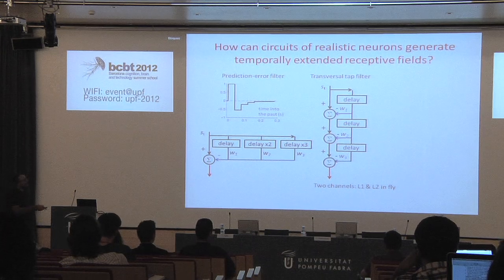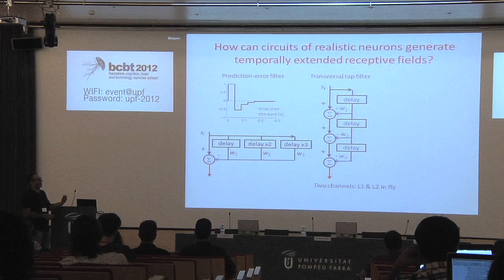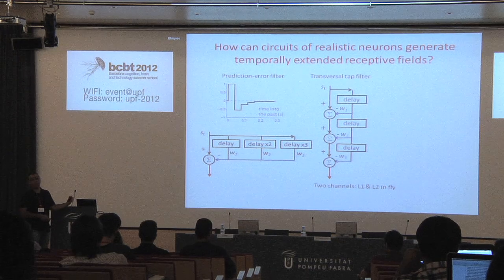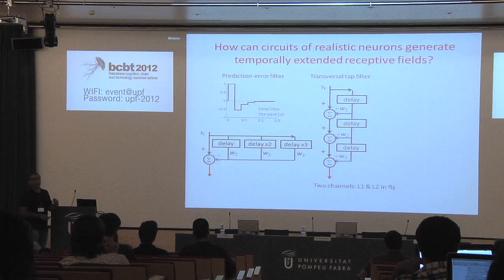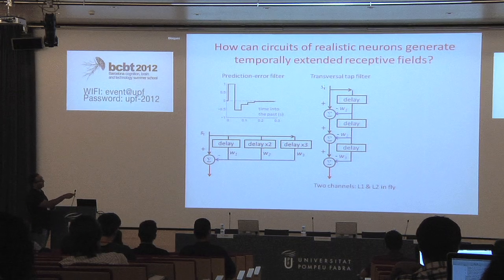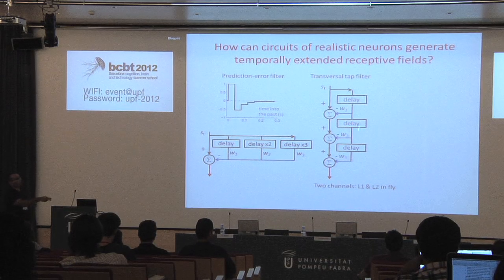Okay. But there is a problem with this scheme, because it kind of defeats the original motivation for predictive coding, which was reducing dynamic range. Because it is true that in this pathway, the dynamic range gets subsequently reduced at every stage by subtracting that correlated part. But in the other pathway, this is the intact original signal just being delayed more and more and more. So you still have to transmit the original signal. Then why do predictive coding at all? Of course, in the end, if you just transmit this, you're fine. But if you're using this model for retina and LGN, it doesn't make much sense.